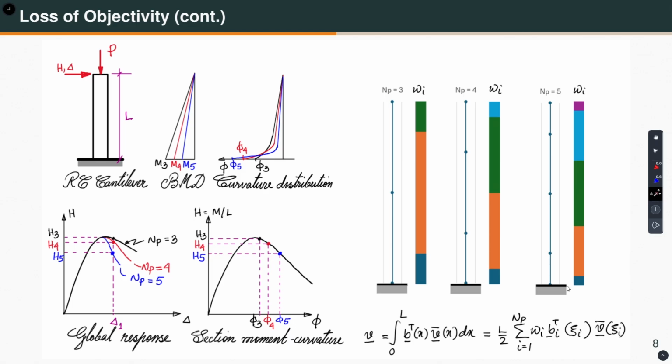Now, when I apply this displacement, I am calculating the element deformation. So, basically this will go like so. Let us say this is the center line, it goes like that, and this is your delta. Consider this to be a simply supported basic system and determine from the chord the element deformation. From there, if it is displacement based, you calculate the section deformation, but in force based, we do not do that. We use an iterative algorithm.